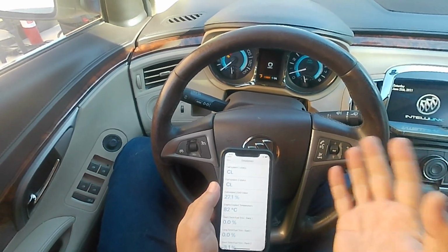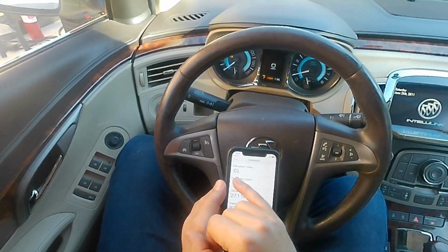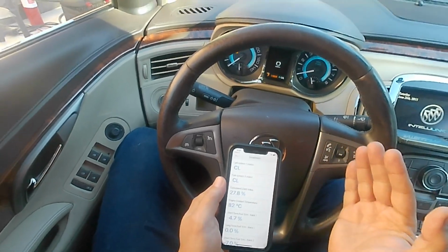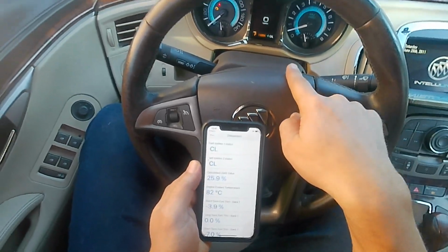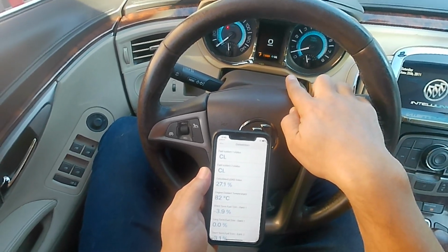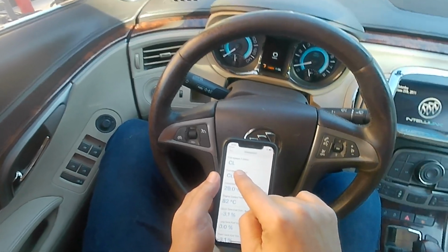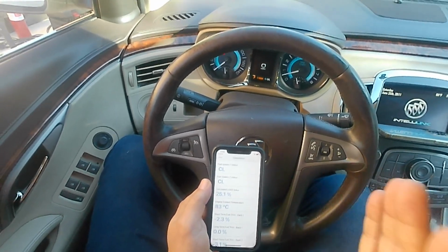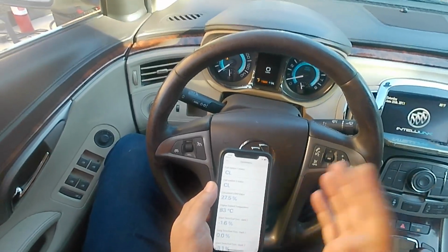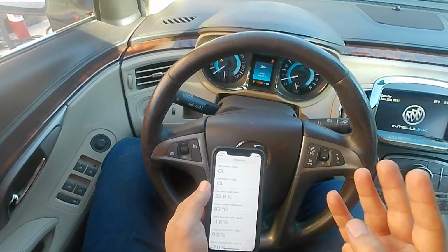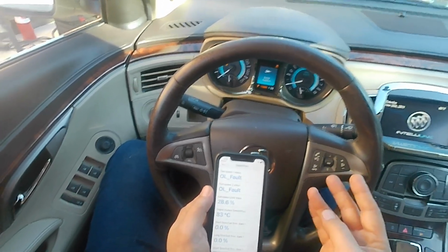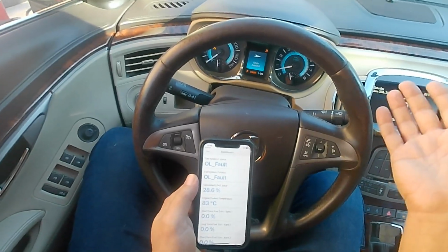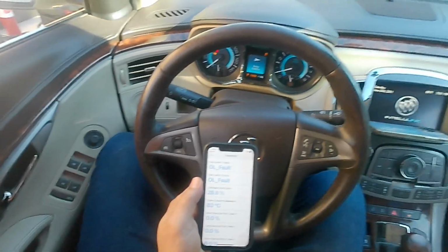So say your intake, now we are on closed loop, so it's coming back and forth, and the warning disappeared. It's going to come back in a second, and we will jump to an open loop, which is not what we are expecting. So anything associated with air intake, with an air leak, I did check with the smoke machine. I didn't have any air leak.